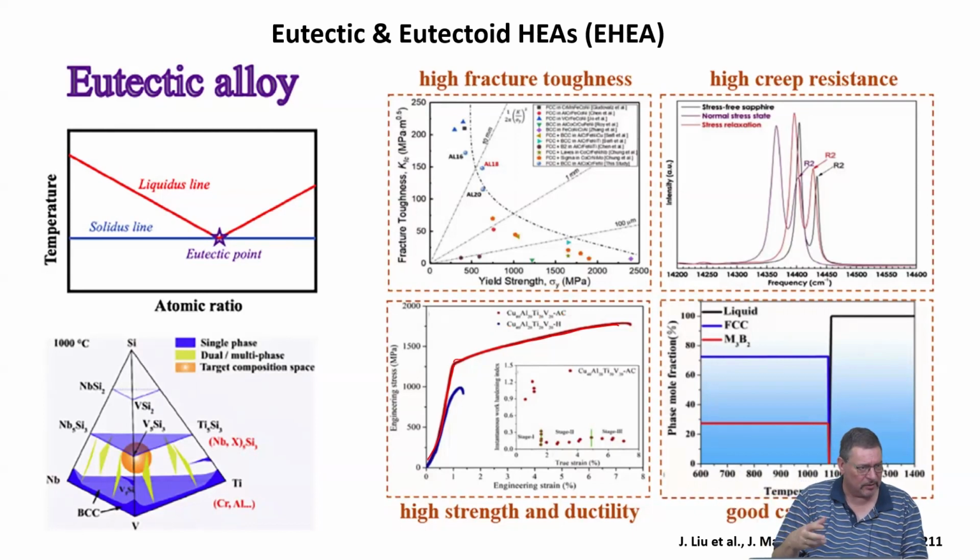So you can make materials which have lower density but still have the same or similar mechanical performance. And high entropy systems always have this tendency that they can be used up to a little bit higher temperatures, because the microstructure stability tends to be larger. So it means it could be, but this is active research. People are not, and I also am not quite sure that this is true in all cases in general. So you could design materials which have lower density but higher working temperature.